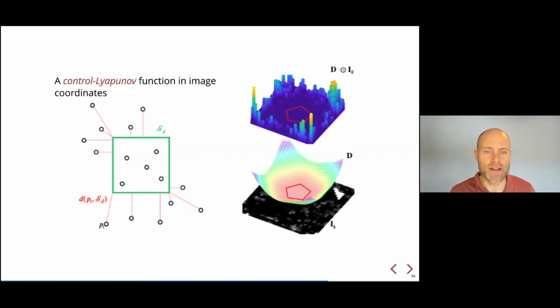The control task here is not very hard. A simple control Lyapunov function, for instance, is one of many things you could do to make it work. The intuition is to assign a score given all the pixels you see from above in that grayscale image. Basically, the current score the controller is getting, the Lyapunov function, the cost to go, if you will, is just the accumulated distance between all the particles and the target set. Once you're inside, it's 0, and otherwise it's the Cartesian distance away. If you think about that in image space, it's kind of elegant: you can just make your cost image and take the Hadamard product with the current image to evaluate your cost to go, or your Lyapunov function.